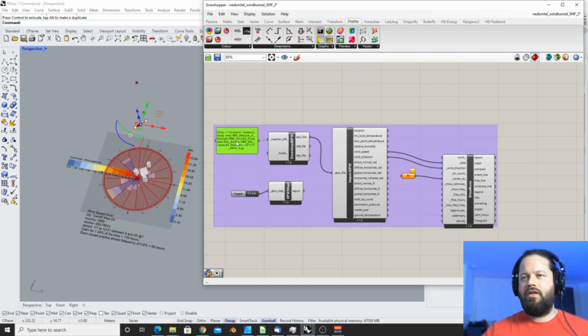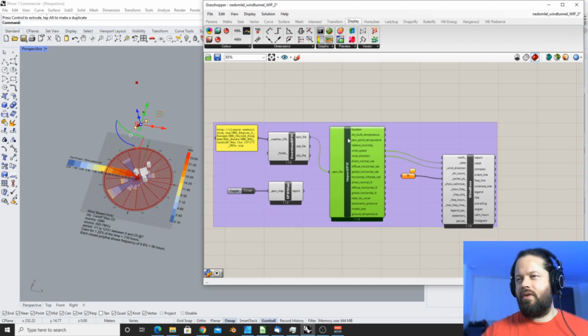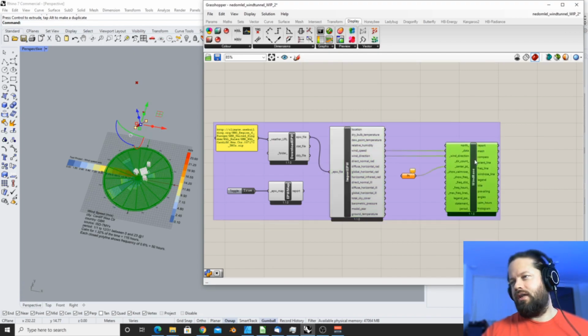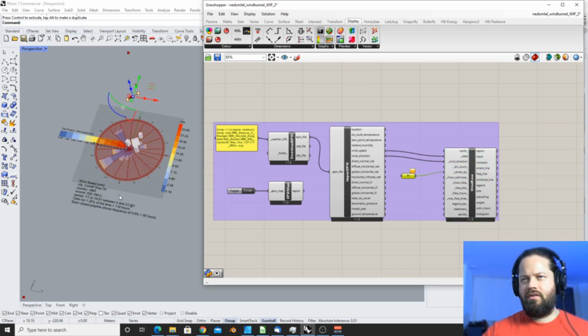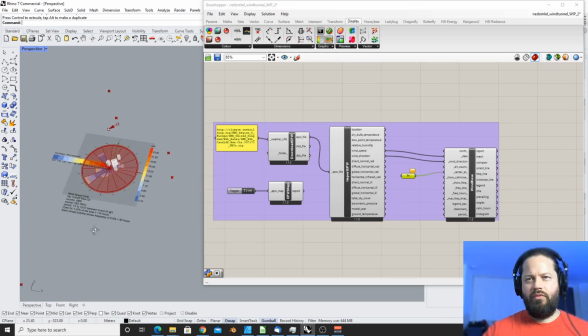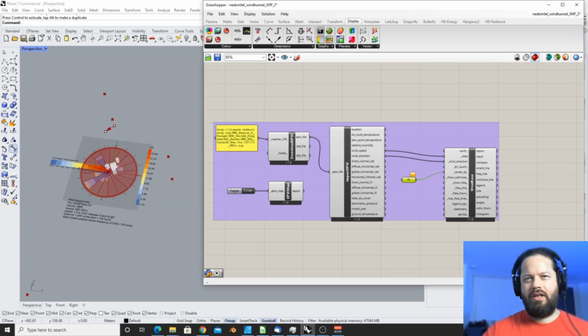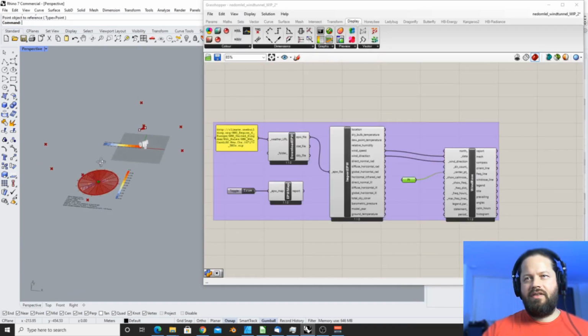So basically it's using the climate data from any dataset you want. We looked also on how to get the map and so on. Then we load this into our E plus weather data file import tool, and that gives us an annual Windrose. And we can of course move this away because we have our model here. So we can move that away with just create a point and maybe move it here.